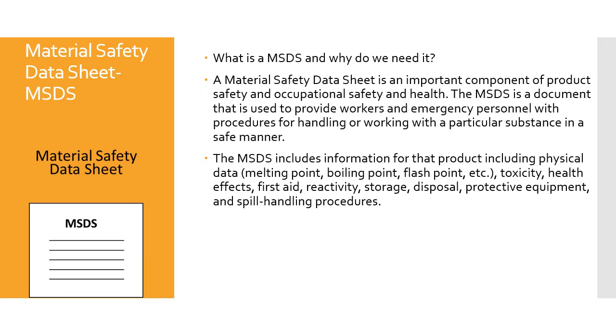And most manufacturing facilities of any size have a place where they store the material safety data sheets. Usually it's the safety office where they keep all these documents and they have a file folder. And then if you bring anything new onto the site, you've got to supply them with a material safety data sheet so that they can add it to their archive of things that they have on site. So if there's any fires or any issues or there's any emergencies, you know what you're dealing with.